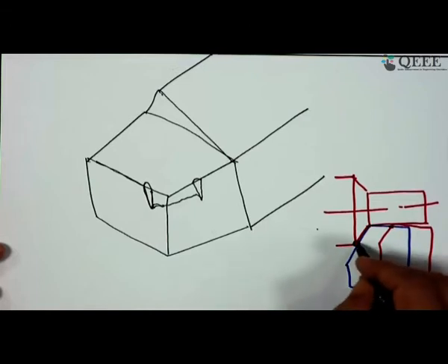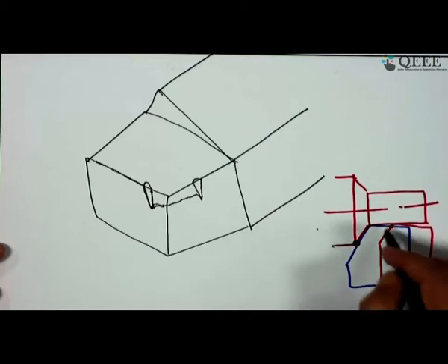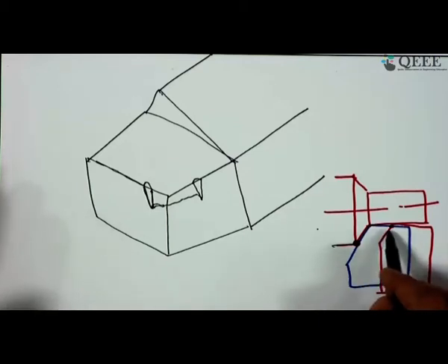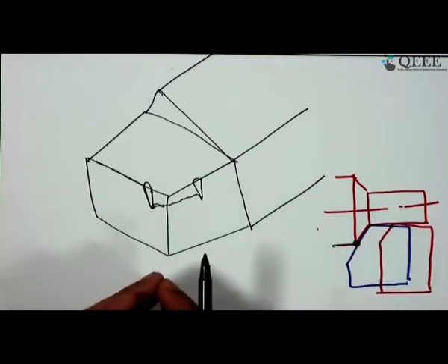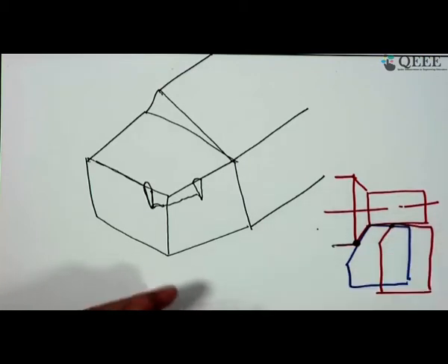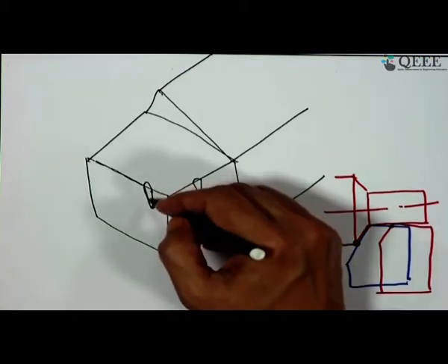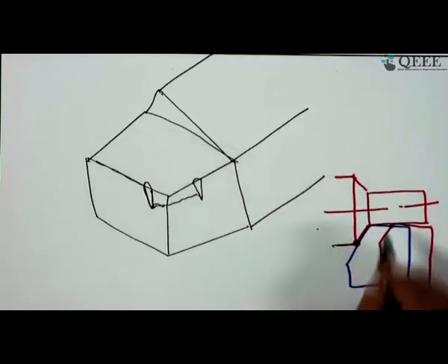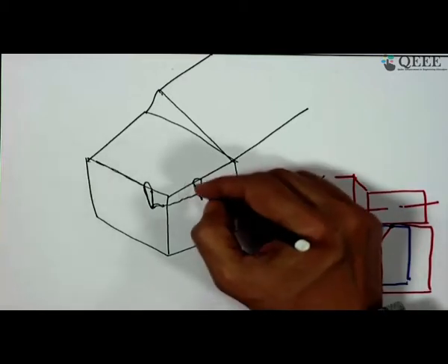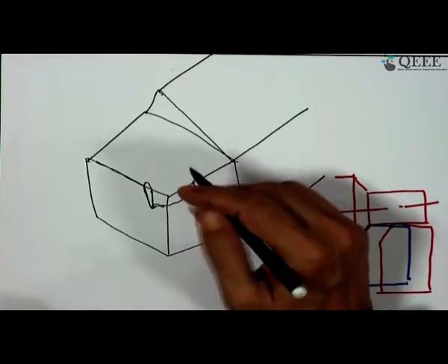One is in the border line of the depth of cut, and the other is where the auxiliary cutting edge and the main cutting edge interact, where they are crossing, intersecting. So, these are the 2 points, after that there is no material. So, at this point you have 2 sharp points which virtually act like 2 knives, and as a result you have a V notch formation.